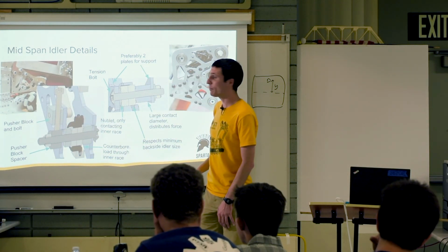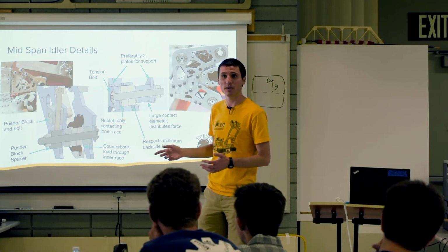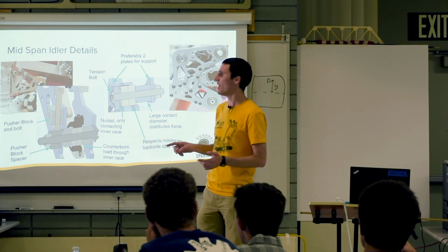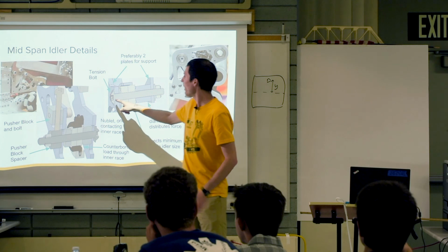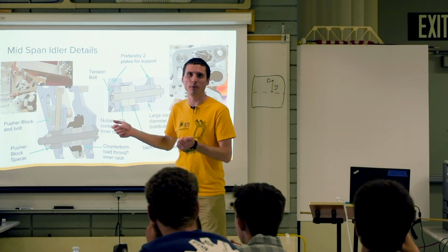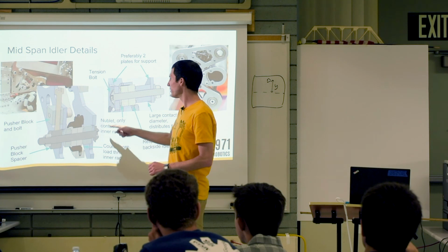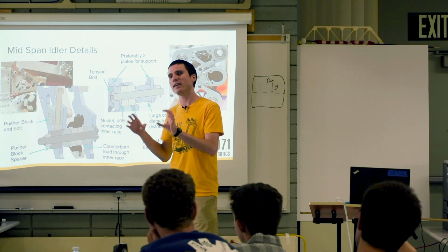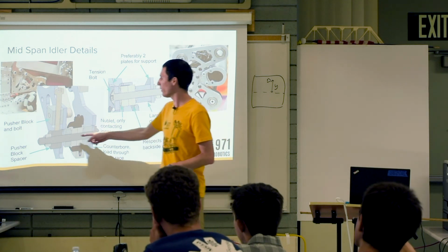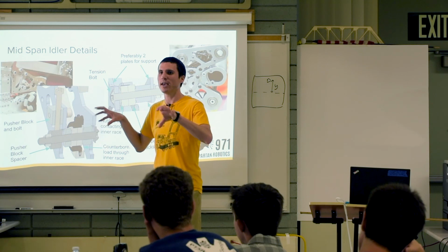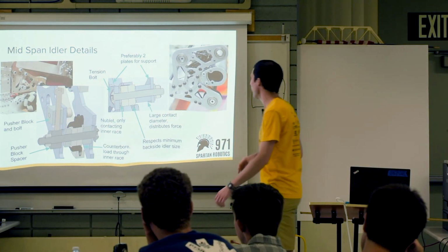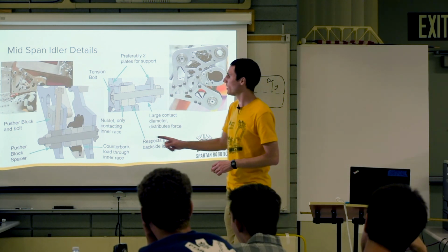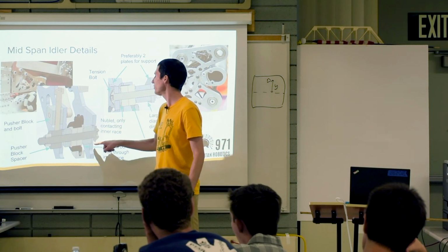First of all, does that make sense to everyone? Okay. So then there are some details within the clamp. One thing we found is that if you have a slot and you use just a button head bolt or a small spacer, as you clamp down on it, the bolt will dig into the slot because your contact area is very low. So we find it's important to put large spacers on everything so you get a good, nice area between the slot and the plate.